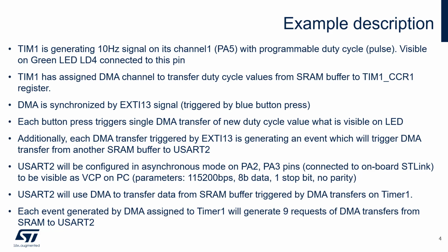So timer 1 will be configured in PWM mode to work in 10 Hz output signal on its channel 1, redirected to PA5 with programmable duty cycle, which is marked as pulse. We can observe it on our green LED on the board.